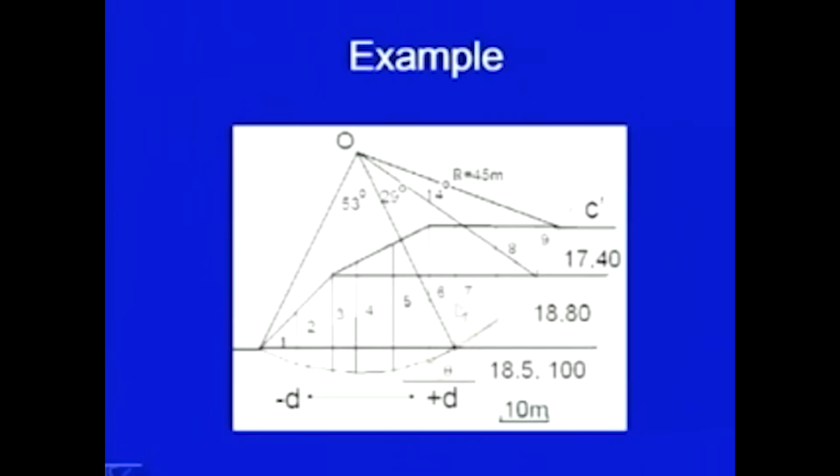We have divided the slope into slices 1, 2, 3, 4, 5, 6, 7, 8, 9. It is as per our convenience, and as discussed last time, for the sake of making the computations simple, I have taken one slice ending here where the profile is ending. Same way one slice should end here. You can have uniform width also, and here also I have taken this at the intersection.